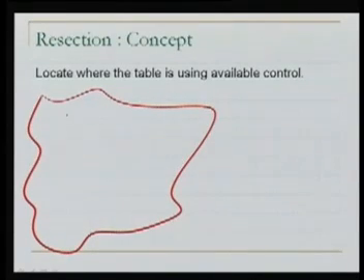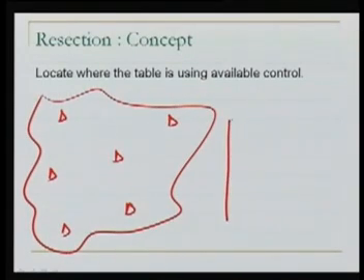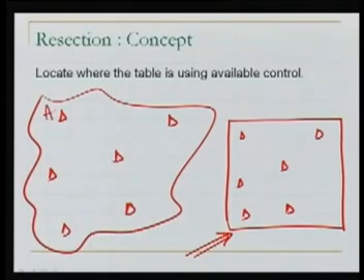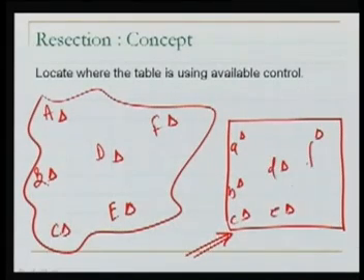In this ground, by some method we established a set of controls. This method could be triangulation or traversing or any other method. And this set of controls is plotted on our plane table. The meaning is, we have got these controls plotted here. Now this is the drawing sheet, and this drawing sheet is attached to the plane table. If this is A, B, C, D, E and F, the points on the ground, the corresponding points are plotted on the sheet.